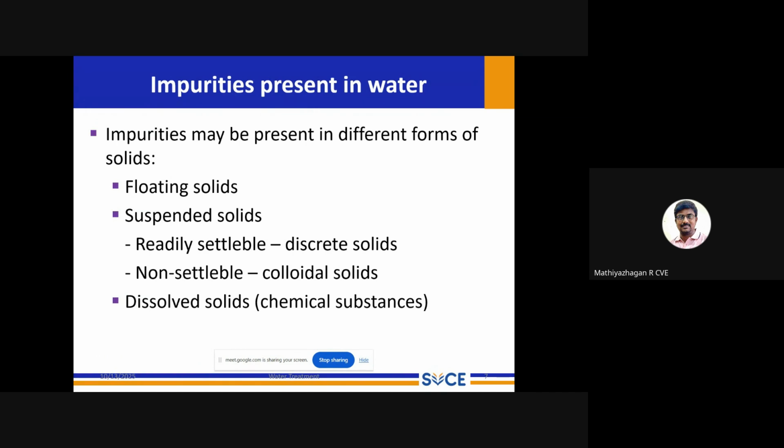Therefore, they cannot settle down, even if we store the water for more than a month or a year. These kinds of solids create a problem during treatment. Therefore, whatever we are going to see is mainly for the colloidal solids. Once we neutralize the colloidal particles, all the other things can happen with no issues.